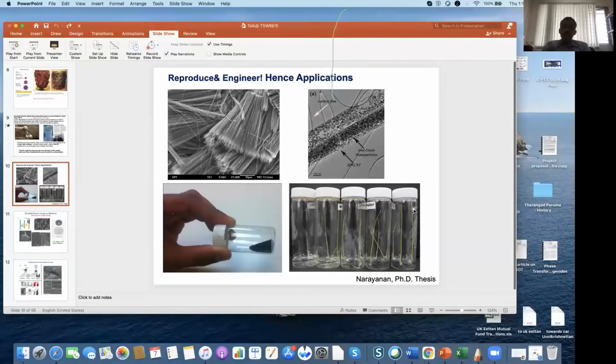One of the ways was to make the oil more thermally conducting while remaining electrically insulating. We modified the oil by using insulating nanosheets of boron nitride, which are electrically insulating and at the same time thermally conducting. So nanosheets or nanomaterials with different properties are available, and according to your problem you can find the material.